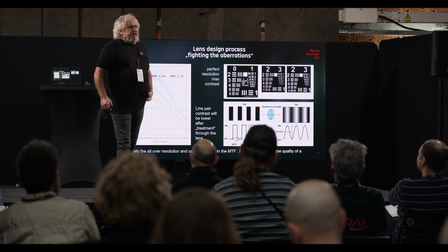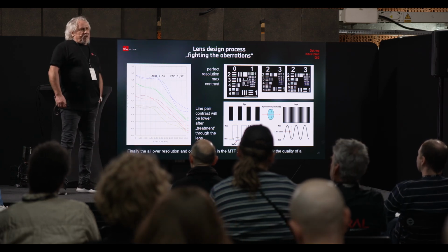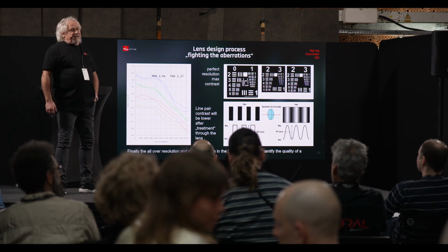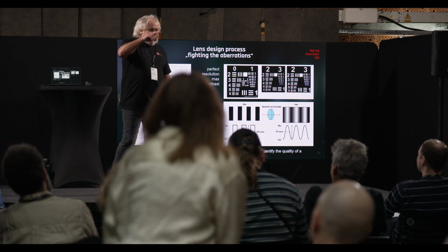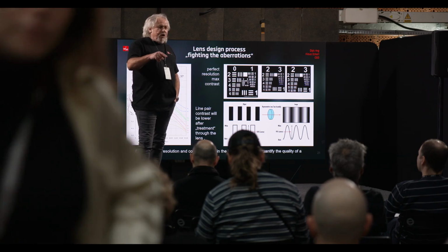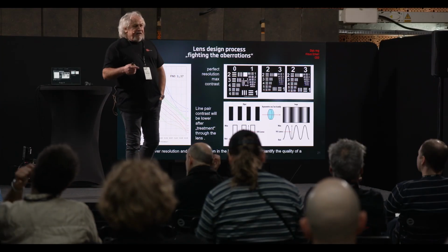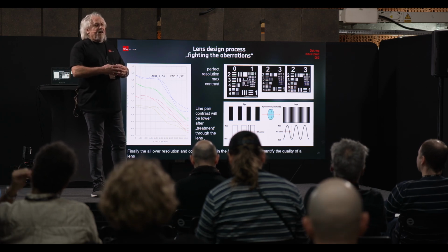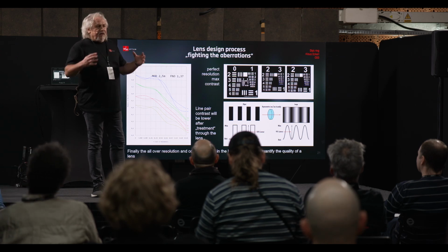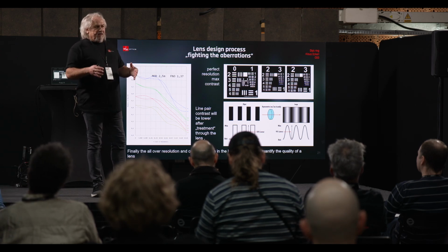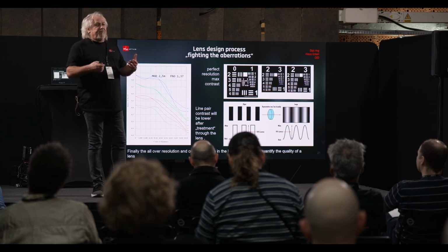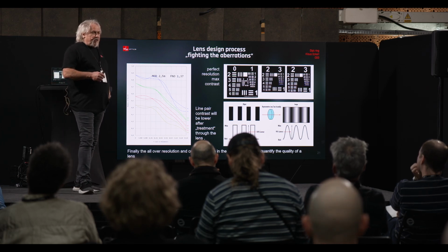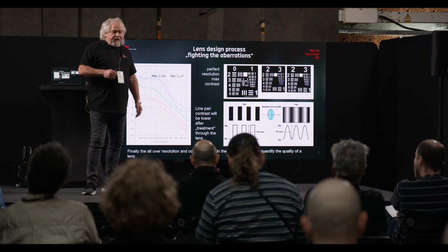For this test, we have a PCO camera, a rather good one. It must be a very, very noise-free sensor for this test. The trick is that you look with the lens under test at a virtual image, and we magnify it with a microscopic lens to get rid of the sensor resolution. So we really magnify this intermediate image with a very good microscopic lens. Then you have to calibrate it once, and then you get much less pain with the sensor resolution. But you're right, otherwise you can't resolve that. Because you must be far beyond what you're measuring. It's clear.